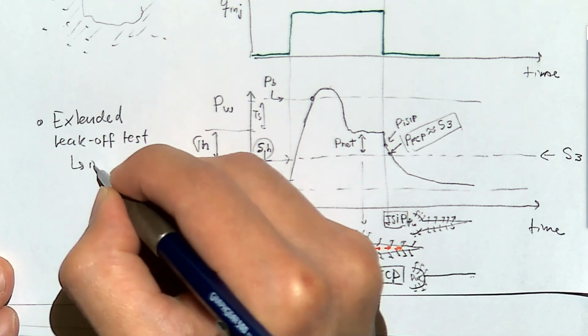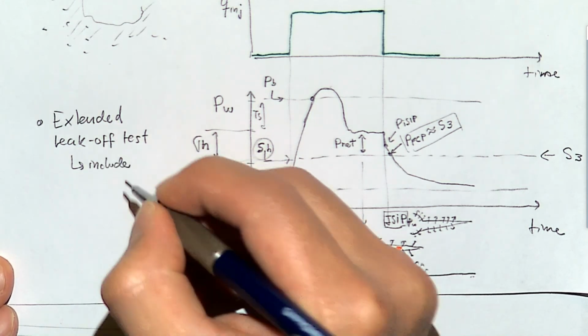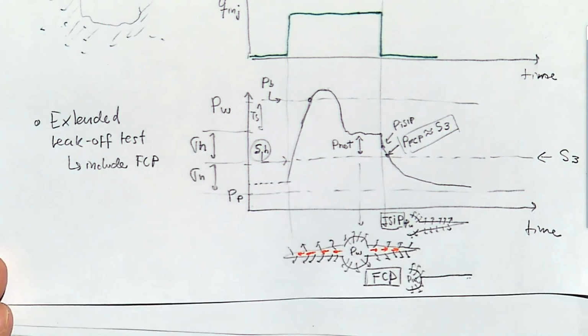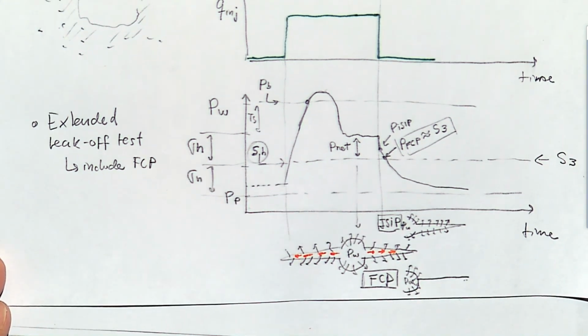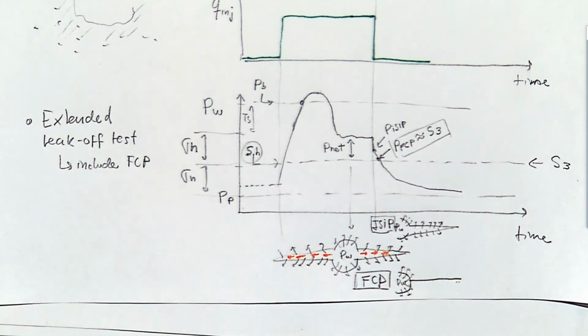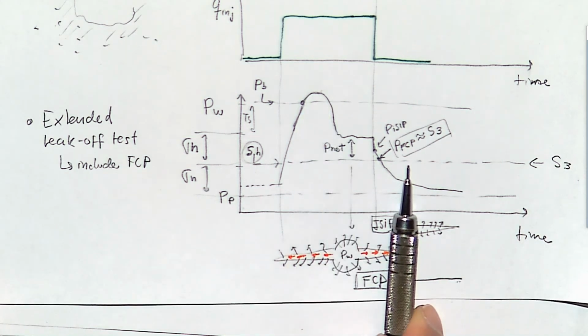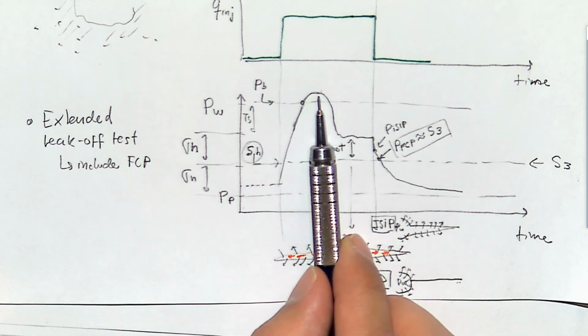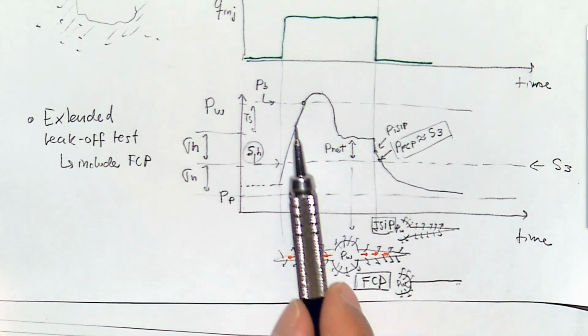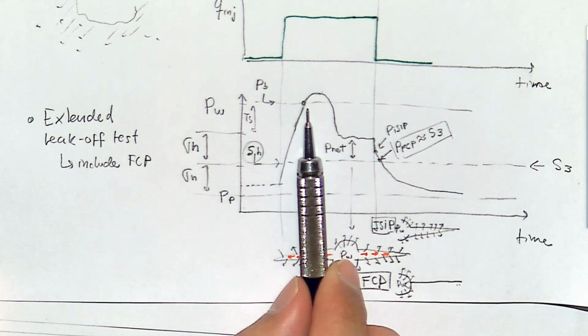And this is going to include fracture closure pressure. But sometimes when you're doing this, if you're drilling into a location that probably you don't want to go over all of this, you may just stop it somewhere over here, just knowing that you just got to the breakdown pressure. Actually, this breakdown pressure is what you will measure in a leak off test.